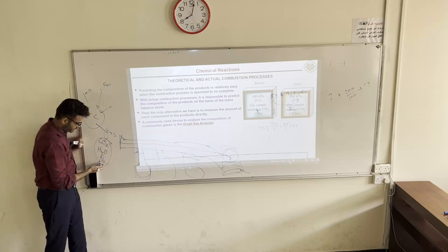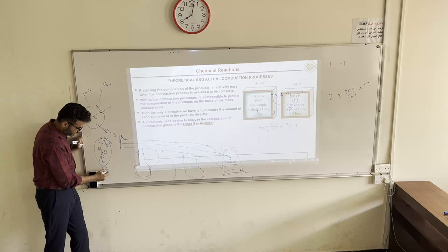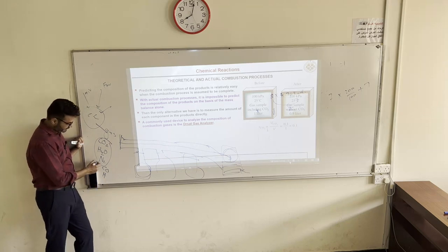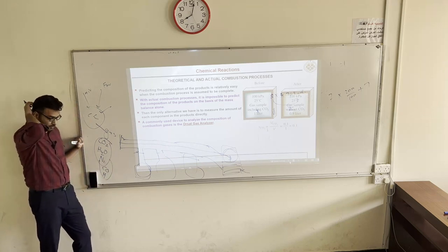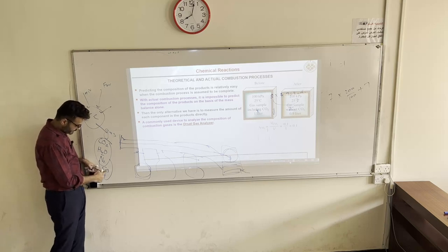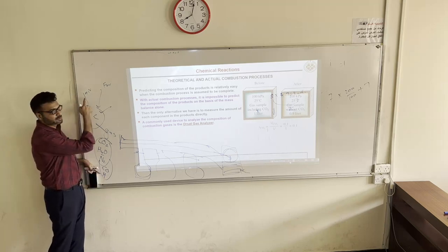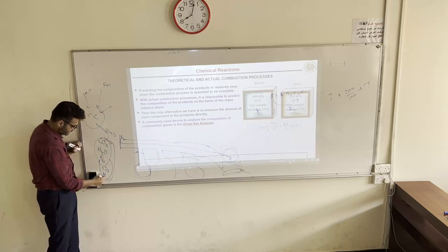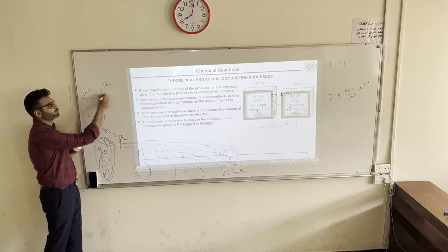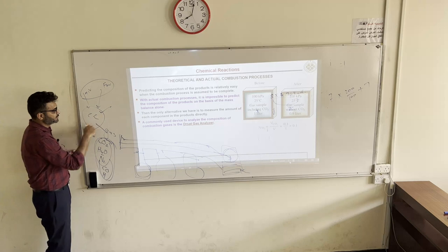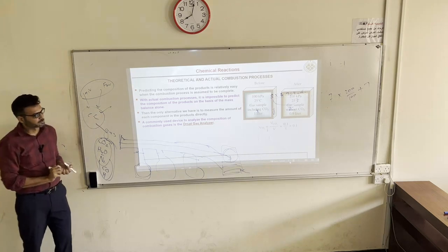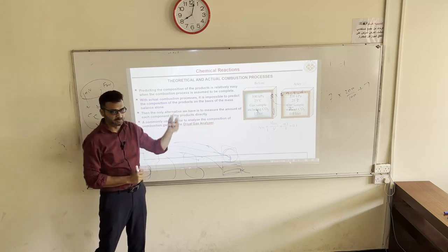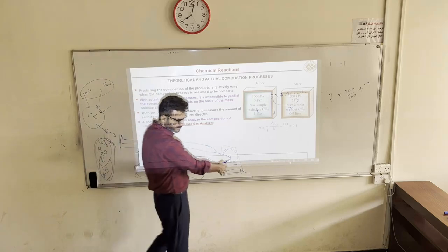By analyzing the exhaust gases, you will know, now I have CO2, but I also have a certain amount of CO or a certain amount of H present. That will tell us my combustion is not proper. And then I need to find out the reason why there is CO or H. Maybe air is in excess or air is deficient. So only by analyzing the combustion products can I predict what is wrong in this combustion chamber. So in actual combustion, that is one experimental technique. I do not remember the complete detail, but that is available.